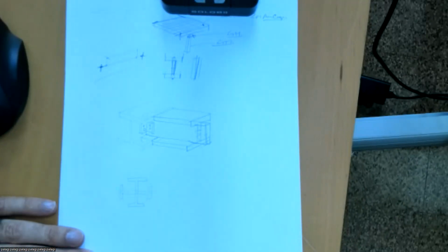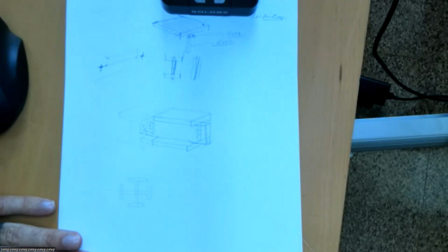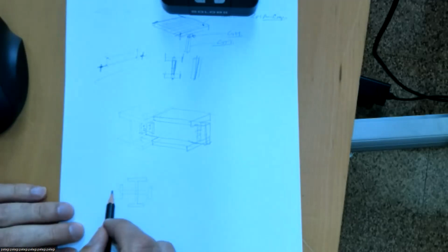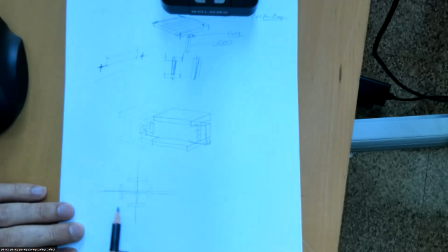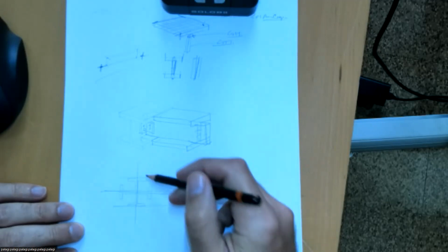Right? So in Revit, if we want to be able to control it later, we need a reference line for each thing. What I get in the habit of, in AutoCAD, they used to be called X refs or X lines. So what I do is start to look at what are the things I want. There's a center line here and a center line here, right? Everything's coming off the center line. Those are the overall width.